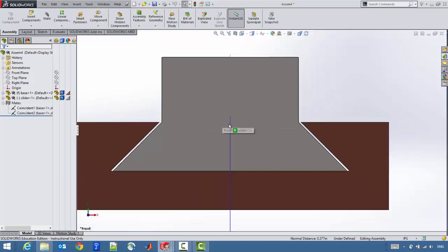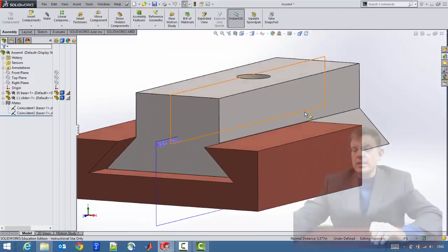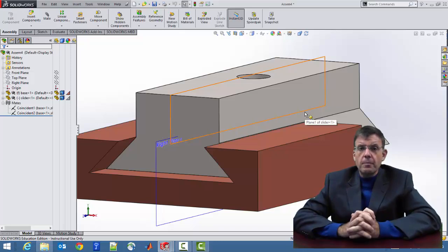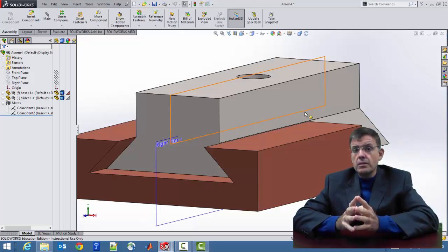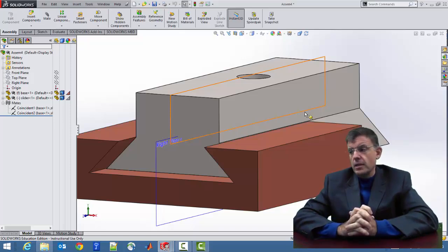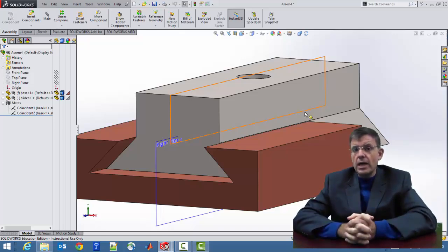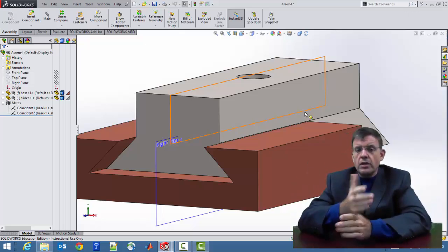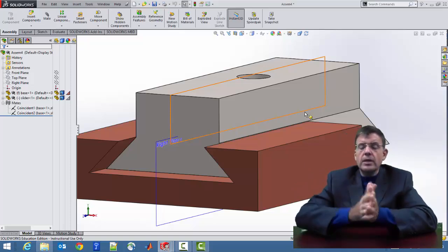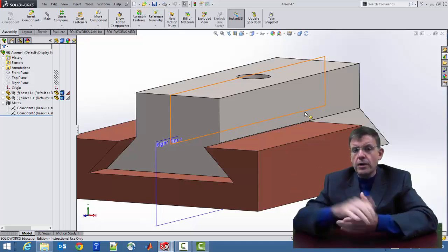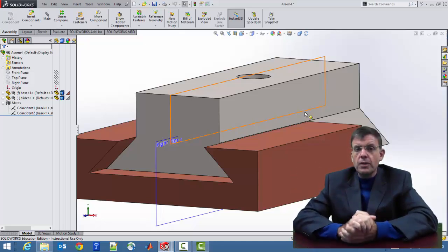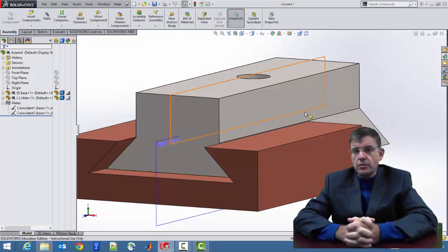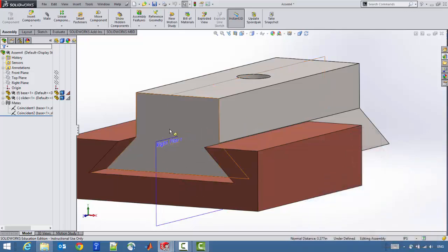Okay, so this was a geometrical constraint. Notice that the constraint didn't have to apply to a feature of the part. The constraint was perfectly workable using reference geometry for that part. Okay, and then finally notice that we didn't have to rely on dimensions. Now, in the process of building these parts, we know what dimension would have caused that dovetail slider to run right down the middle. Okay, but this, I would argue, is a stronger, a more purposeful, a more direct way of embodying the design intent, which is, of course, you intend for this to ride down the middle.